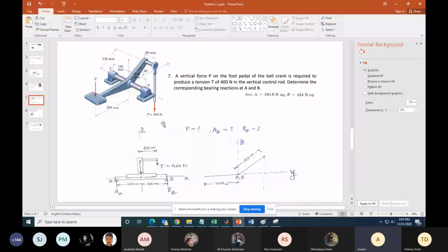Sir, I have one more doubt. This is similar to a bearing, yes? The joints at A and B. So why is there not a moment? Bearings allow rotation. In the notes we were told that it allows free translation along the axis of the bearing.